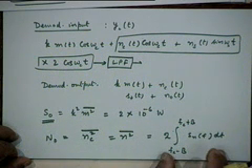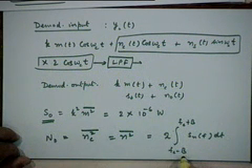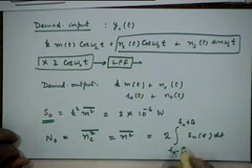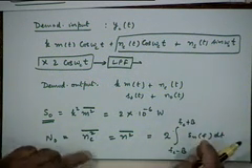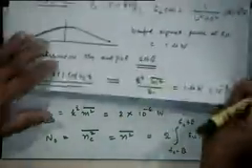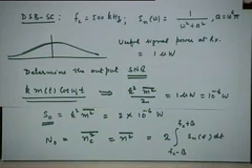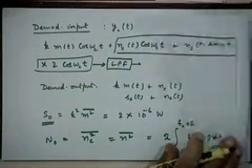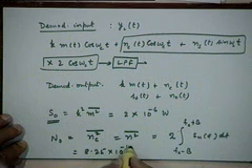So you have to calculate this integral. Fc here is 500 kilohertz, B is 4 kilohertz. So this becomes 496 kilohertz here, and this becomes 504 kilohertz here. So you have to take this expression for the noise power spectral density function and integrate it over this domain, and the numerical answer that you will get, let me write it here itself, will turn out to be 8.25 into 10 to the power minus 10 watts.